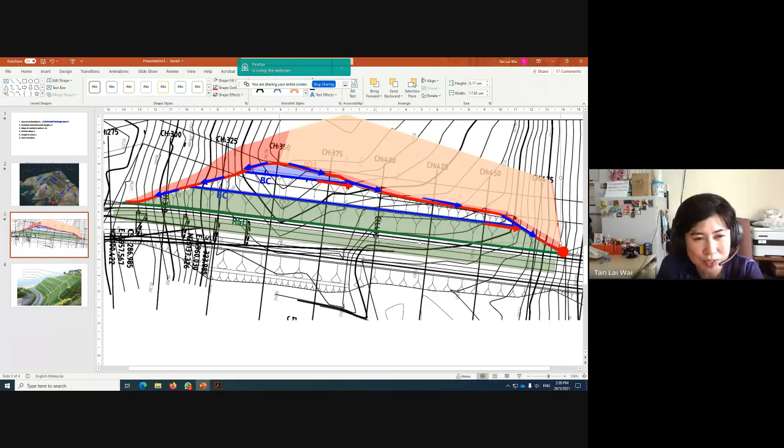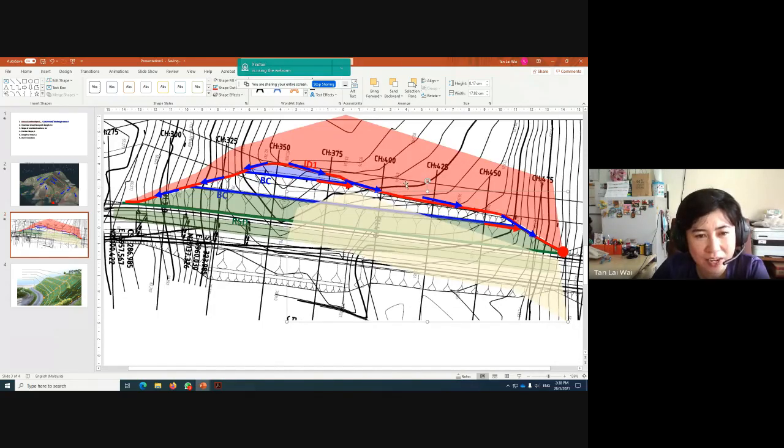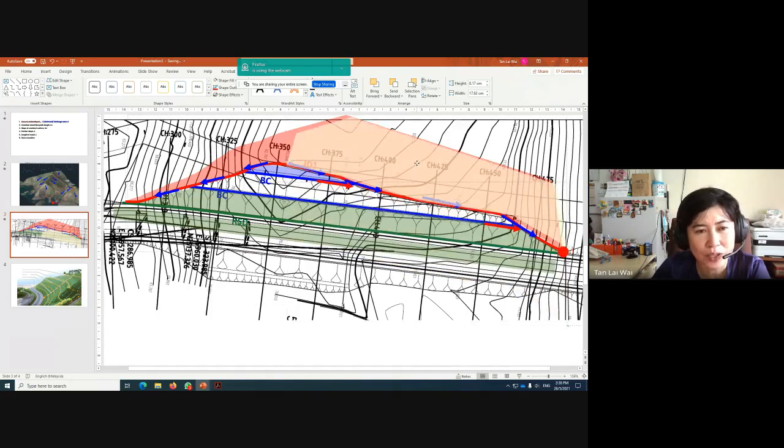Or, supposedly, you need to consider the slope. You could tentatively assume what the slope would be, then divide by the slope, or account for the slope, and then you will get a larger catchment area. Oh, okay, that's better. As an engineer, you should consider that, because it is safer. Any more questions for your question one?